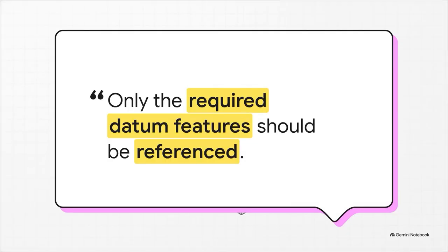It all boils down to that classic engineering mantra: garbage GD&T in, garbage simulation out. A single bad feature control frame, a forgotten diameter symbol, or a misunderstood datum reference frame is going to completely skew your entire result. Say you reference a datum feature out of functional order. The software will still happily run 10,000 builds, sure, but it's going to constrain the virtual parts incorrectly. So your input quality is absolutely paramount. All that symbol-level knowledge you've mastered is exactly what makes these advanced tools work.